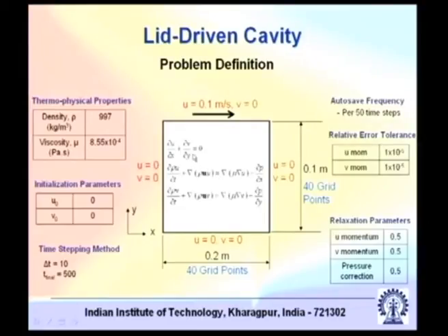Usually now the question will come, how will you ensure that your results are fine, because you may use different grid points and you may end up getting different solutions. The answer is that at the end you have to establish that your results are grid independent. That means if you use a refined grid and you get a solution, then you have to show that with further refinements of different levels your solution does not change, and that is called a grid independent solution. So grid independent solution is one of the benchmarks of accuracy in a CFD problem implementation.